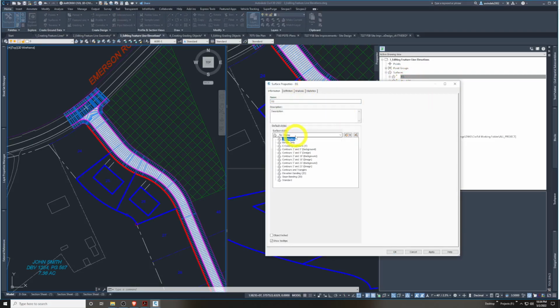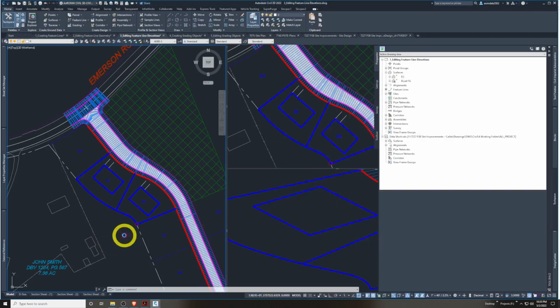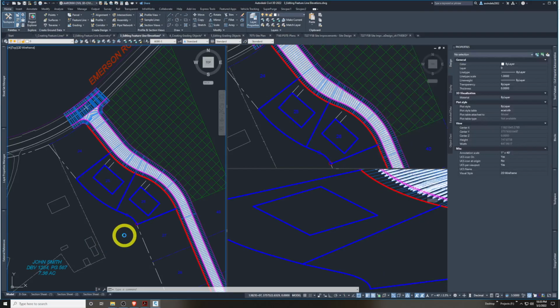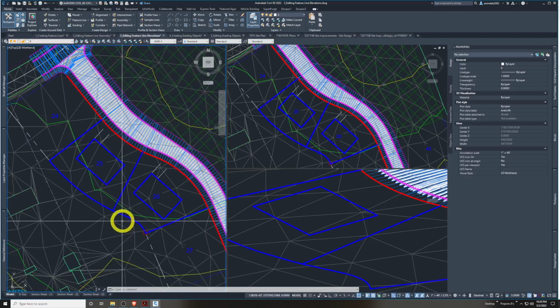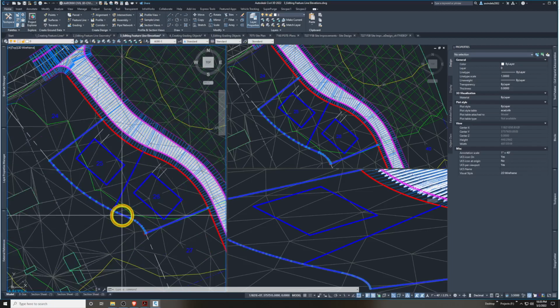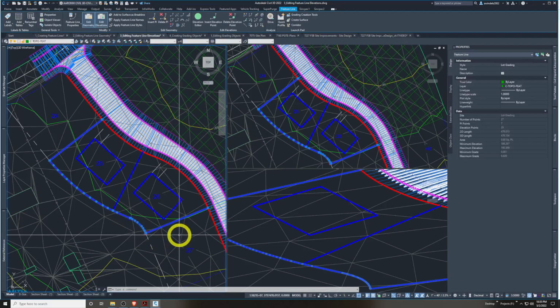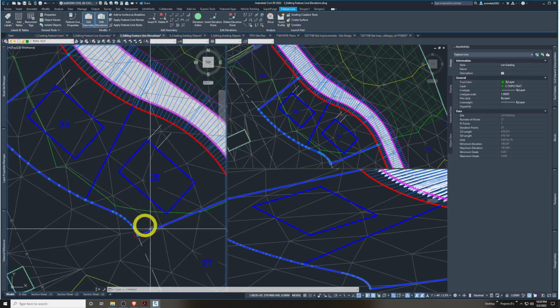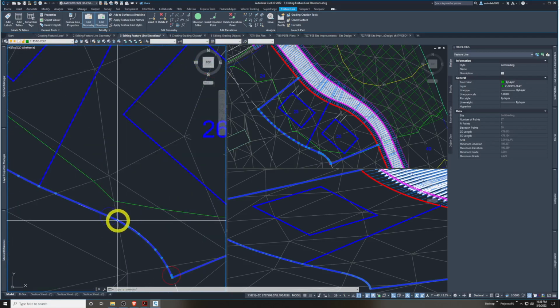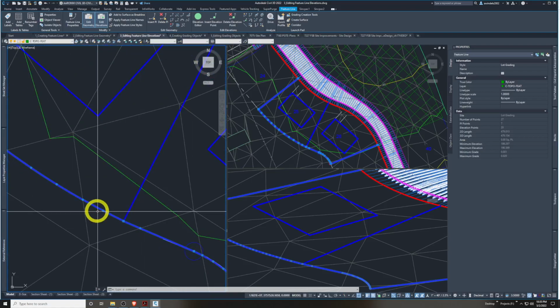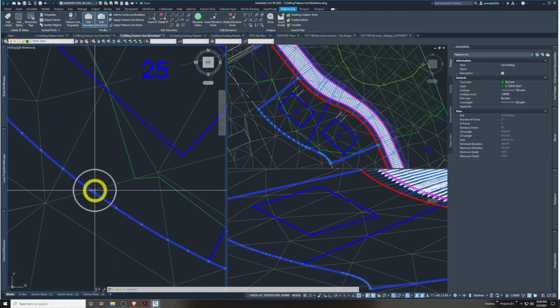Let's just change the existing ground surface quickly here to something with triangles showing in the Civil 3D surface style. Let's give it a second. So anywhere there was a significant grade change, it added contours or circles, but it also for sure added one on every tin triangle where the existing ground surface crossed a tin triangle.